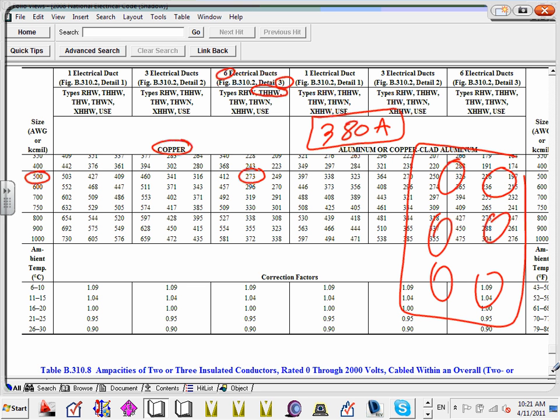A lot of people have used 380, guys, as kind of a rule of thumb, but it's really not. What we did, again, at Elevator Bucket, we use a software called AmpCal. We build the system. We have a 12 duct system. I want to carry them with 500 amp. We run it, and we see what the size of the conductor is, and how much current the conductor can carry under these circumstances.